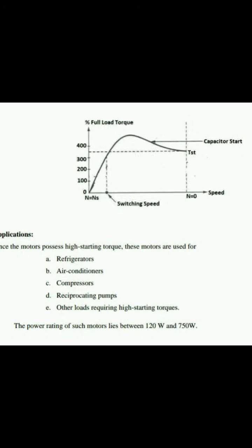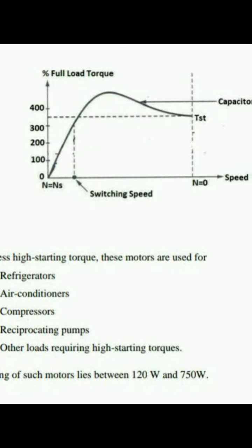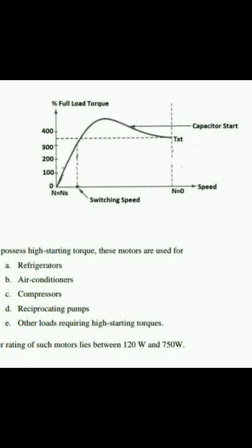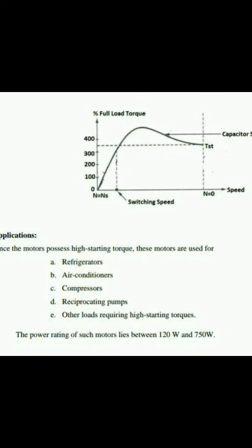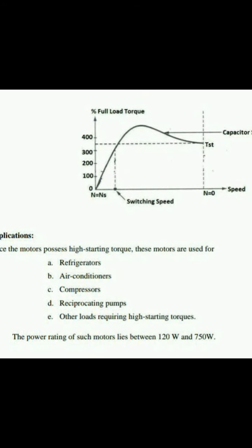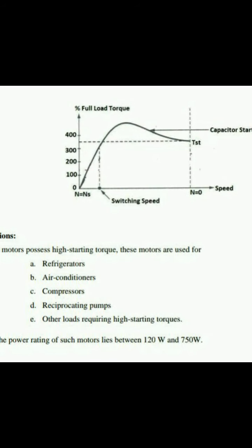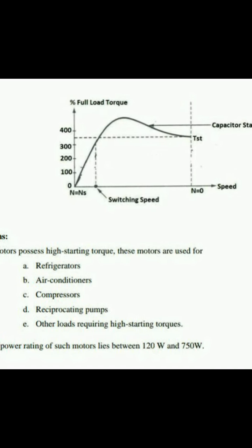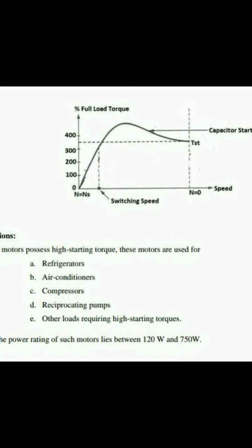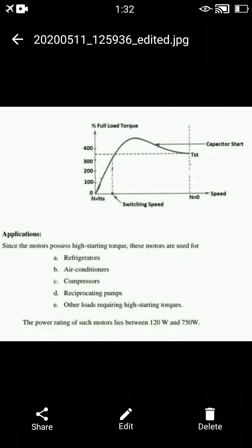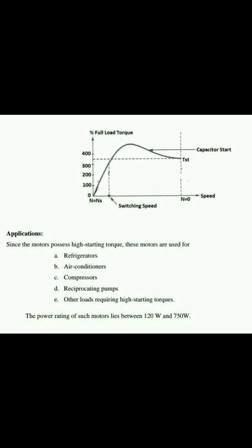So this is the torque speed characteristic of a single phase induction motor, the capacitor start induction motor. When the speed is 0, the starting torque is near 0. Due to the capacitor starting, the torque increases with speed, and after reaching the maximum torque, it reaches the synchronous speed, and this is the position at which the centrifugal switch will operate. So this is in concern with the capacitor start induction motor.